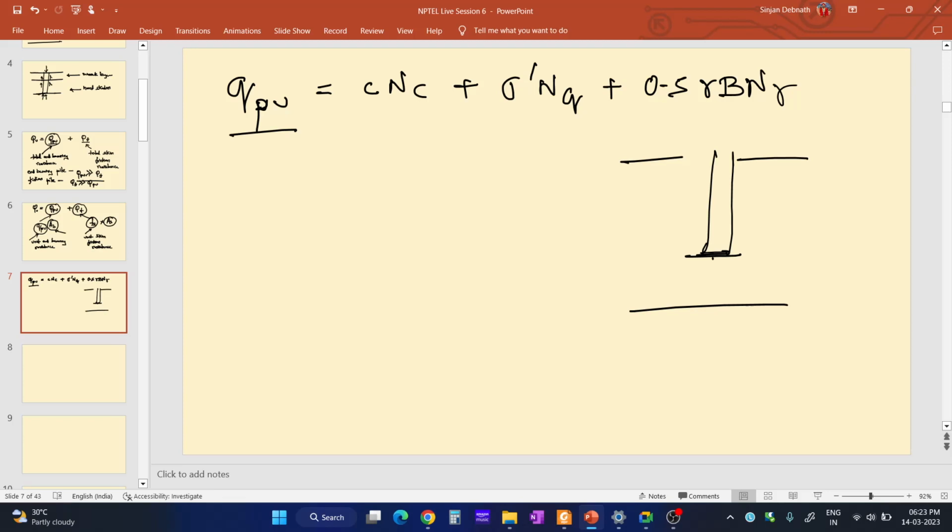So we can say this has some end bearing or bearing capacity. You can also use this bearing capacity equation for shallow foundation in this case, since the tip of the pile is in contact with the soil. So you can find the bearing capacity using this equation.